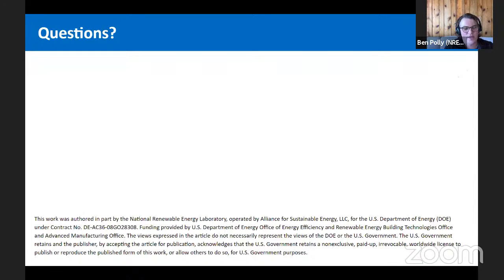That translator is under active development, so we're still pulling together capabilities there. Once it's translated over, you would be simulating the district thermal system utilizing Modelica and Modelica solvers. And if you're modeling the individual buildings, then you'd be utilizing Spawn of EnergyPlus instead of traditional EnergyPlus. Hopefully that helps answer your question.